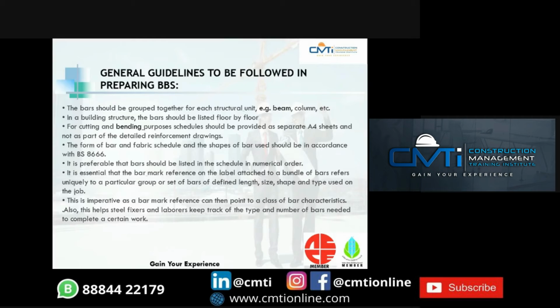It is essential that the bar mark reference on the label attached to a bundle of bars refers uniquely to a particular group or set of bars of defined length, size, shape, and type used in the job. This is imperative as a bar mark reference can then point to a class of bar characteristics. Also, this helps steel fixers and labelers to keep track of the type and number of bars needed to complete a certain work.